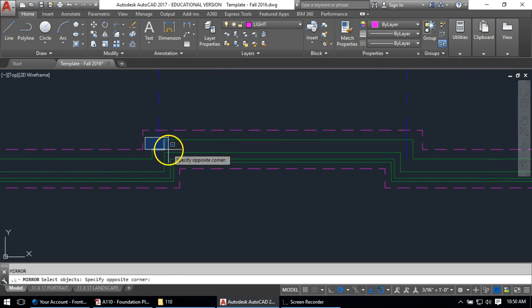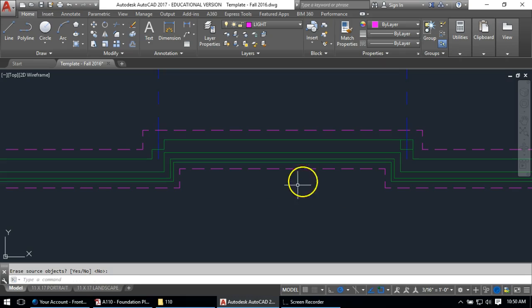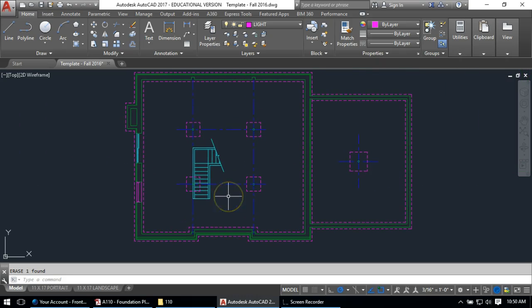And since this is in a shape like such, I can mirror from a line that I haven't trimmed, say one of these exterior lines, down to make it here on this side, and trim this out. If I trim that first, I didn't need to go to erase, but since I have that piece there, I will erase it. And there we go. I've made those little notches for what will be the structure.